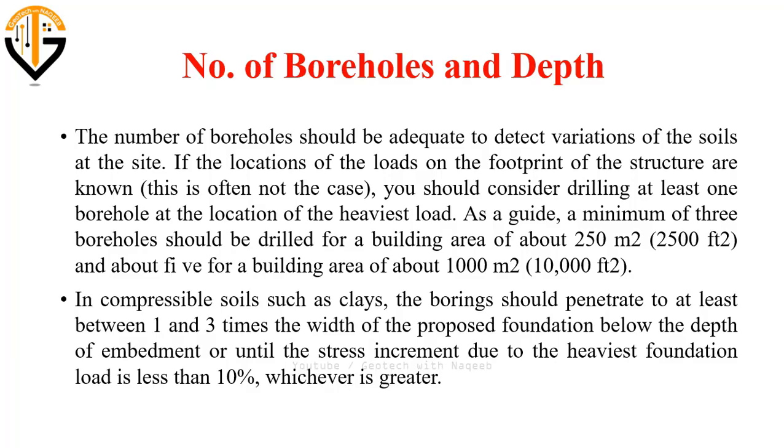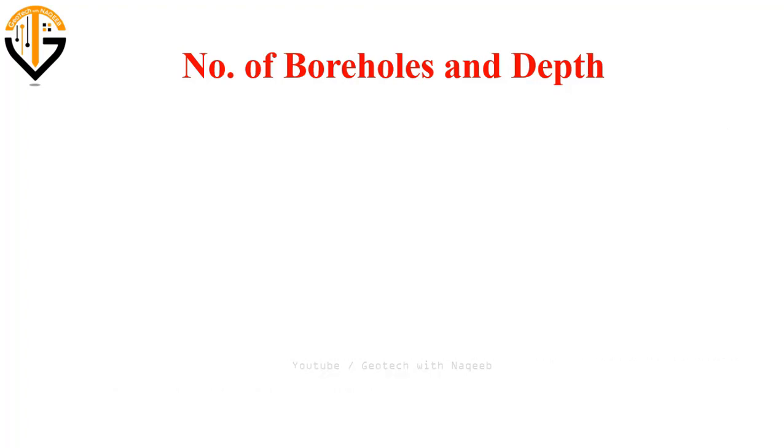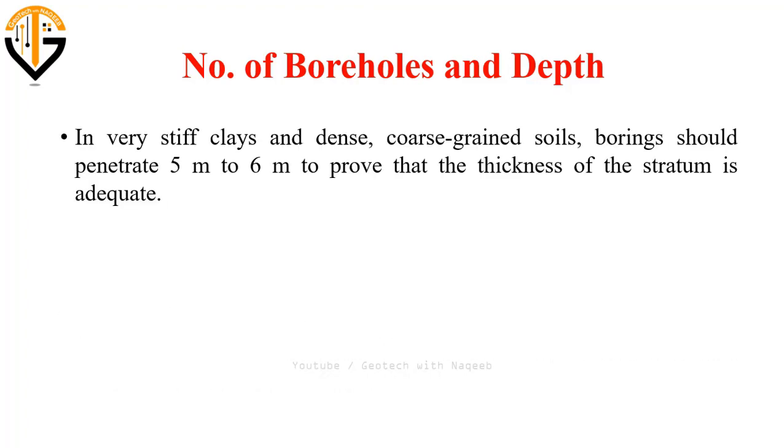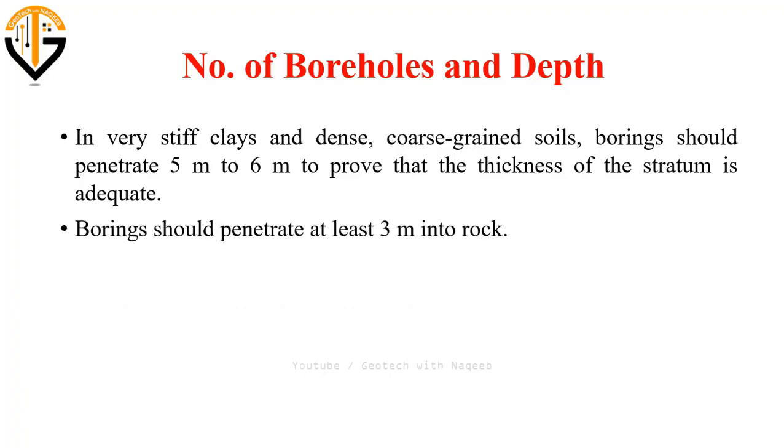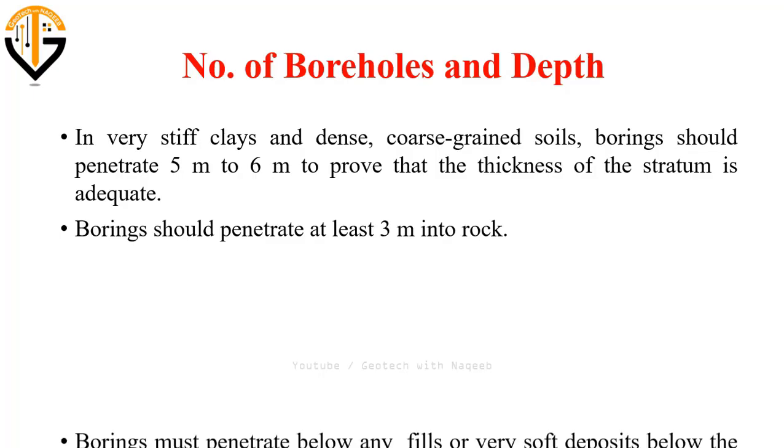So let's say if the width of the foundation is 2 meter, then the boring should penetrate up to 6 meter. Similarly, in very stiff clays and dense coarse grained soils, boring should penetrate 5 meter to 6 meter to prove that the thickness of the stratum is adequate. Borings should penetrate at least 3 meter into the rock. If rock is encountered, then the boring should penetrate up to 3 meter into the rock.